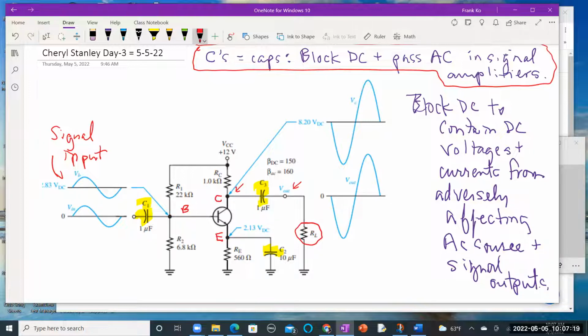But when we measure at either of those places, the waveforms on the output tell you everything. Remember, C3, like all capacitors, blocks DC. There is no DC on the right side of the capacitor. So when we're measuring our signal out after the capacitor, you have 0 volts. That signal, the blue waveform, is riding on 0 volts.